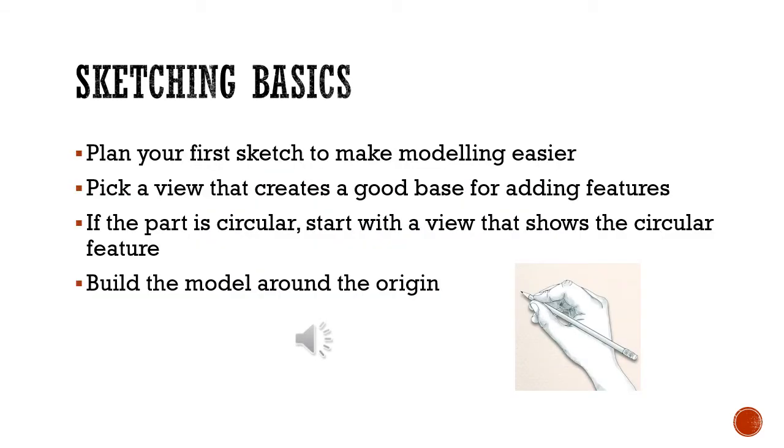Just a quick review of some of the basics of good sketching practices. I would tell you to look at what you're trying to create and plan your first sketch. The first sketch is kind of important. It will help make the model easier if you have a good first sketch. Try to pick a view that creates a good base for adding other features to the part.